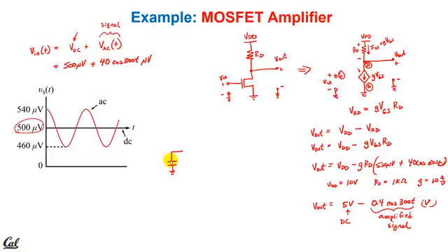Well, that means we have a pre-charged capacitor. Doesn't that mean it has a voltage? Exactly. If you're not doing anything to it, if the thing is just sitting there, that little thing has some, call it VDC. It's some voltage that's stuck across there permanently. All right? So far, so good? Yeah, okay. Now, before we talk about how it does sound, what also is inside the can is something like, it can vary a little bit, but something like a little FET.